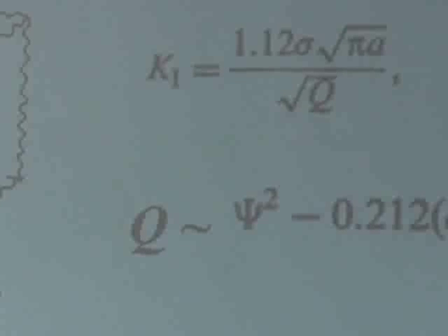And both happen. I didn't scan it, but there are plenty of examples of tanks that were nice cylinders and they spread apart because at some point the crack became unstable. You reached the fracture toughness before you started leaking and lose pressure.